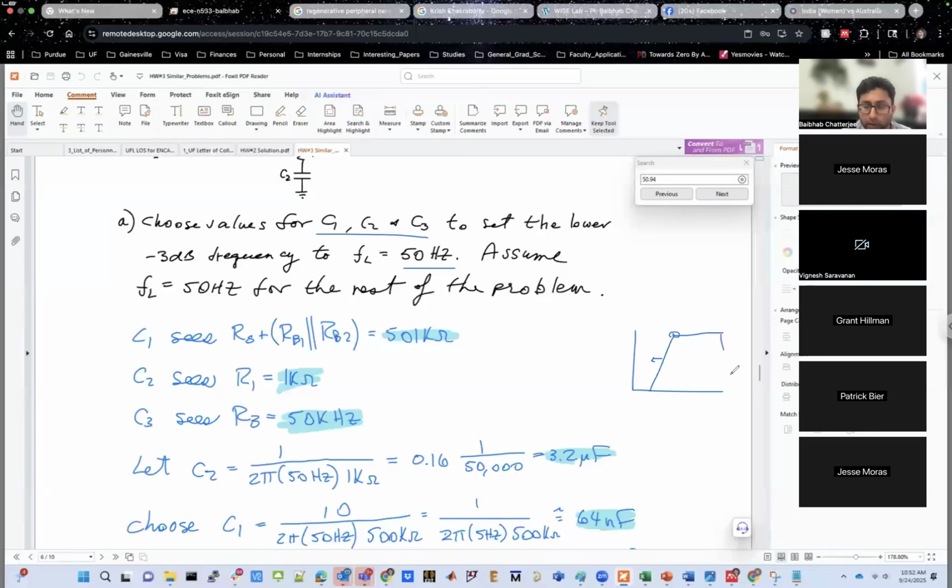If it were a low-pass filter, that is, you are considering this part, again, the dominant pole over here is at this point, and then you would consider any other non-dominant pole at much, much higher frequencies. So that is the reason why, let's say you are choosing C2 to create the dominant pole. You can choose any other capacitor as well. It does not matter. Everything is a correct answer. You just have to choose one of them.